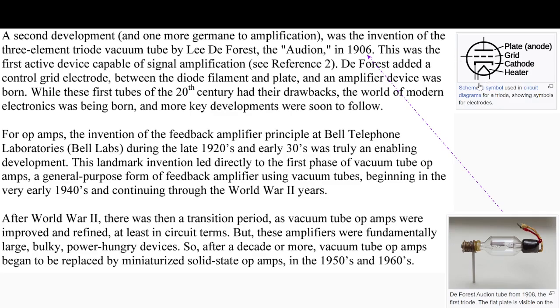So what will happen? The electrons come out from the cathode, because that's the purpose when we apply voltage, negative to the negative and plus to the plus. That's the nature: the negative electrons flow towards the plus charge. So if there is no grid, it's a natural flow. This grid was introduced to accelerate that flow of electrons going from cathode to anode.